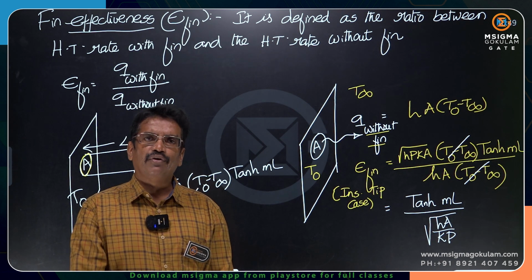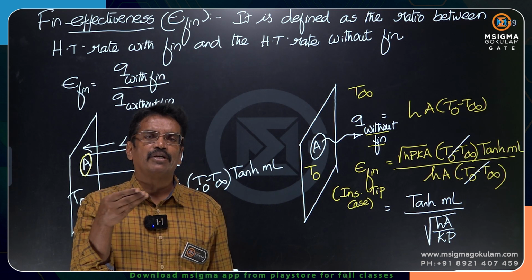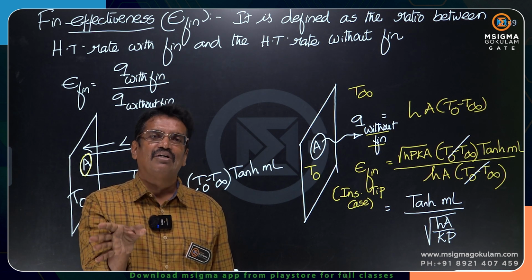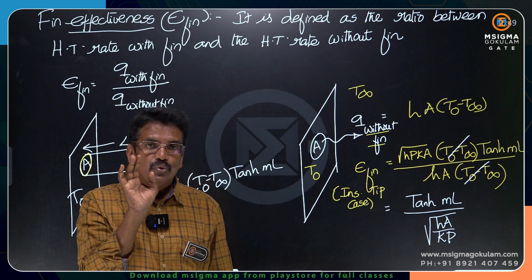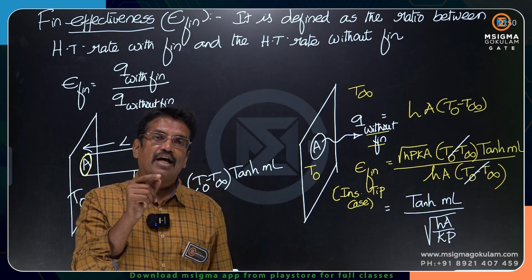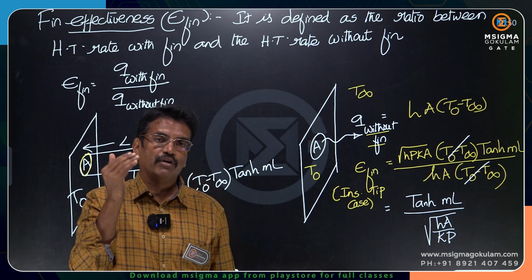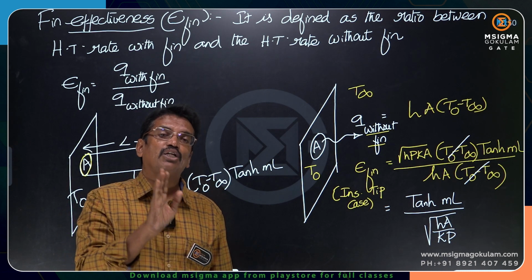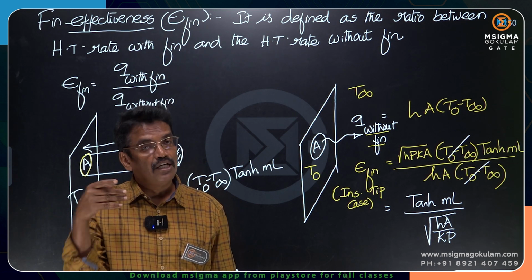If the effectiveness of the fin, I say for example, is 1.1, then what is the percentage increase in heat transfer rate by keeping the fin? 10%. So I can judge that yes, it is a waste of keeping the fins. If you want to say that fins are really helping us, heat transfer rate at least must increase by double. Minimum it should get doubled heat transfer rate as compared to the case without fin. After keeping the fins, heat transfer rate must definitely get doubled. Then only I can say that fins are worth keeping, fins are really helping us.